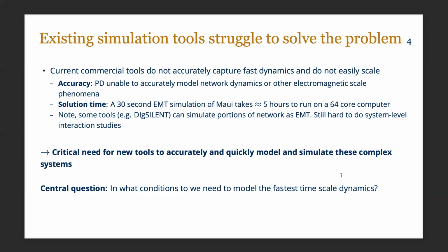And then if you think about solution time, an EMT simulation could capture all of those dynamic phenomena, but because EMT simulators work with very, very small time steps, a 30-second EMT simulation just of the island of Maui could take many, many hours to run, even on a large machine.